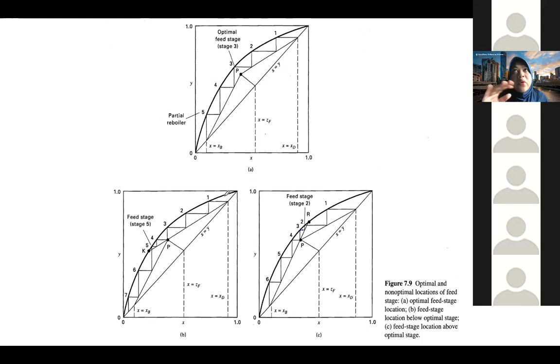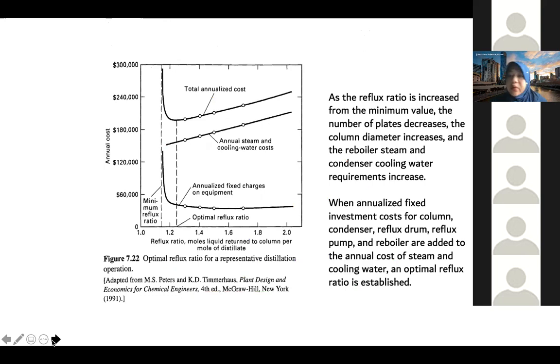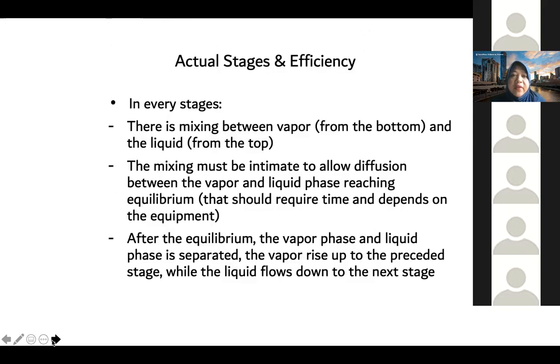But how to get that is more like problem solving. The engineer in the field deals with fluctuation of composition, feed, for example, or maybe one tray is broken and it just gets left out, so then the number of trays is actually less than one, and so on. All right. So we have this continue. Then I'm going to continue with the next one, the reflux ratio also from yesterday, around 1.25.